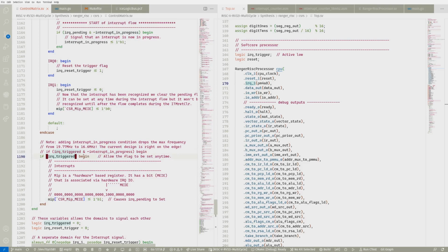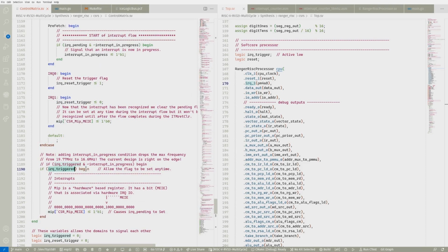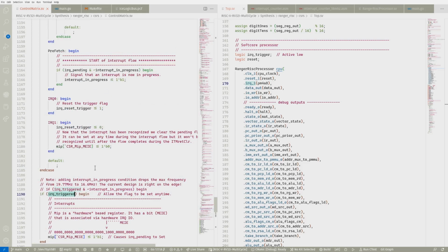The downside to that means that if your interrupt signal is coming in so fast and frequently that your actual code starves and the only thing that runs is the interrupt routine itself, that's generally not a good design, but it works for us in this case. I can actually add this back in and restrict it. But if I do add this in, we'll actually lose interrupt requests as they're coming in. So this one allows us to, in the future, add in a queue such that every time a triggered IRQ comes in, we actually queue it up and allow it to process any of them. But this is a super simple design, and I only wanted to get it started.